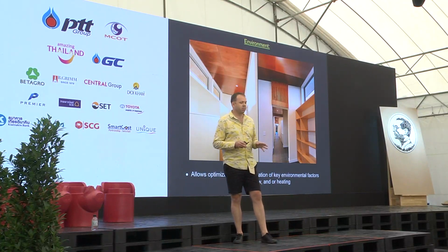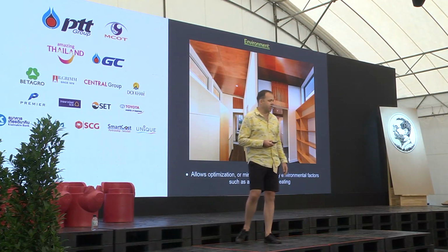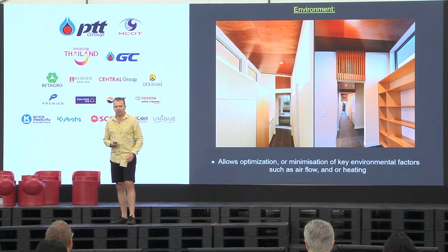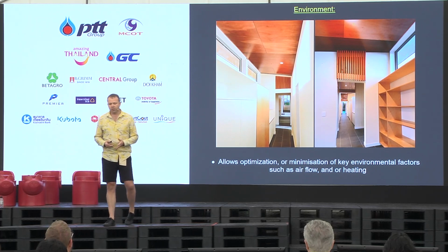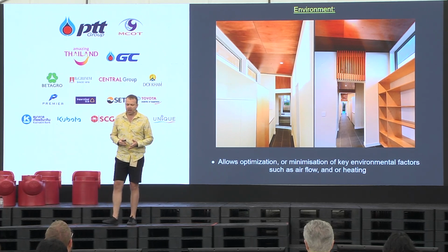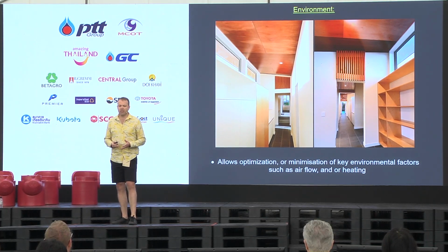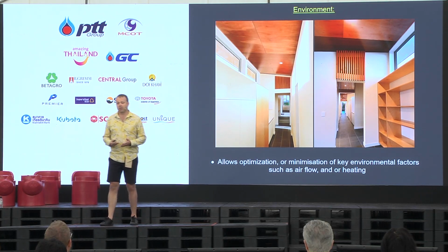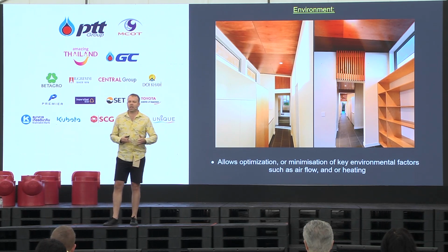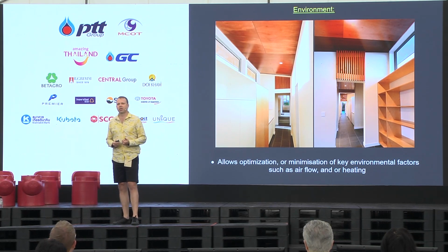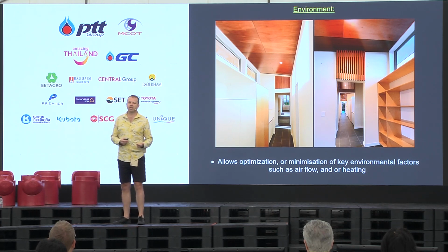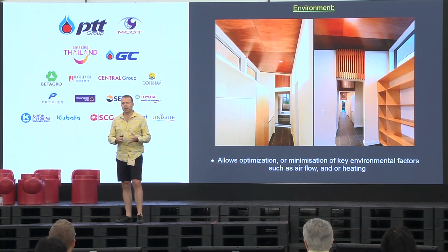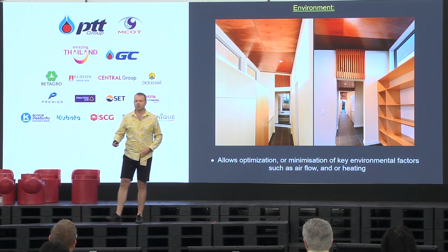Each site is different. This is another house in New Zealand, and what we're looking at is optimizing and minimizing the amount of technology that we use in there. And what we've done here is we've essentially designed out the air conditioning system. And what it comes down to is correct insulation technologies, glass technology, understanding how the seasonal winds are going to work at different times of the year, different times of the day.